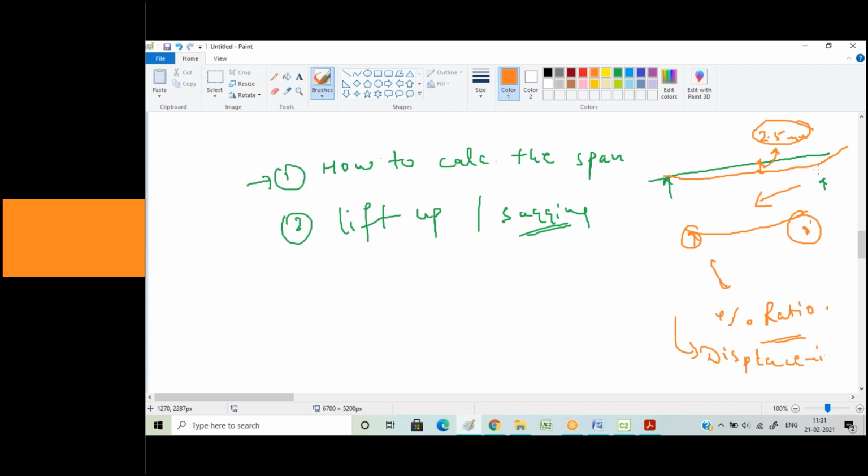That is why I said a piping design engineer thinks, okay, fine, whatever loads I have placed are absolutely okay, but that might not be the case, because whatever standards we are referring to for calculation of span have certain criteria that say if your line is 4-inch and your material is austenitic steel and your temperature is this much, the supports have to be between this and this. Okay, but a very important value that has been ignored, or rather is not pragmatic, is your density.